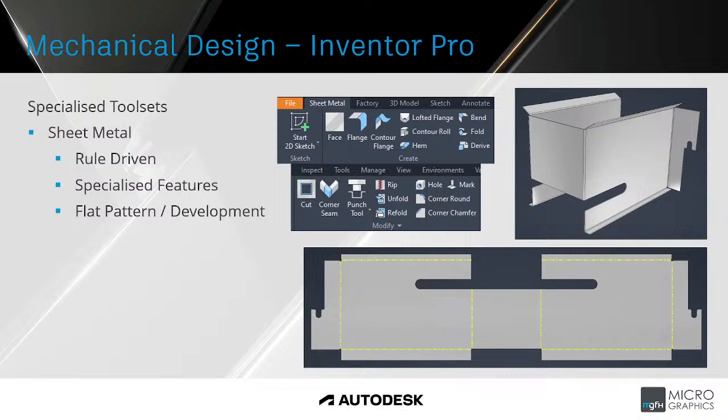Then within Inventor, we have more specialized tool sets. In this case here, I'm highlighting the sheet metal toolset. So we have sheet metal specific commands that can be used to create sheet metal components. We can then flatten them out. Now these sheet metal components, they are rule driven. You create rules to specify the thickness of the material, the bend radius that should be used by default for the material. And from there, we can use the specialized features like contour flange, various options there to add more